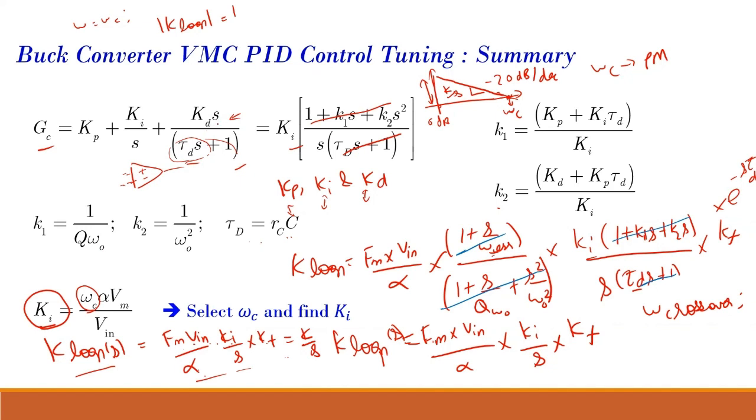High frequency is basically noise. In a differentiator, if it directly responds entirely to the noise, it will result in improper operation. Erroneous results will happen because noise is random and not desired. So to attenuate that noise, we add this low pass filter.